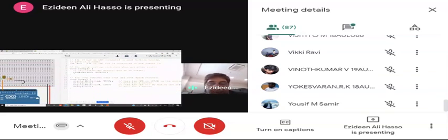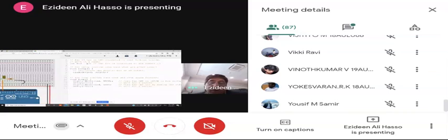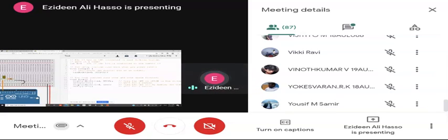And here I'm defining this pin. When we look at the pins of the Arduino board, we consider ourselves as if we are sitting inside the CPU, looking at the outside world from inside the Arduino. Since I'm looking from inside outward, pin number 13 is actually an output.